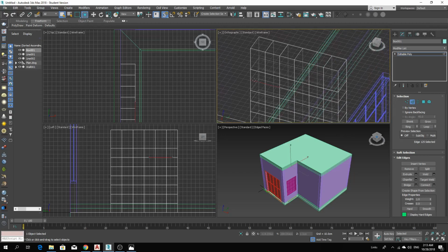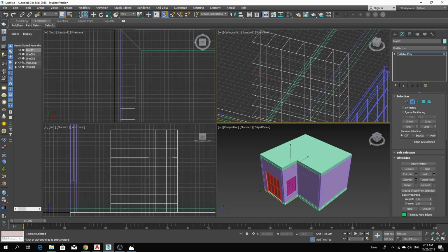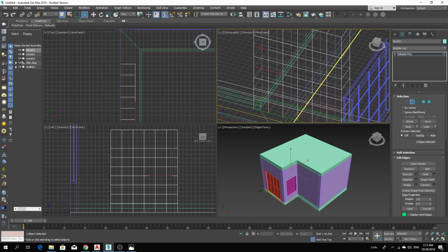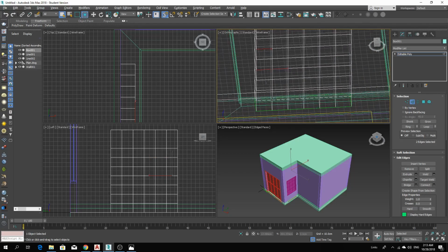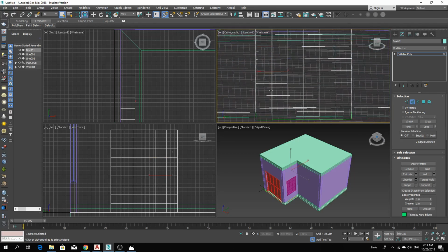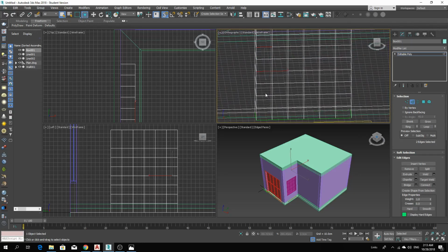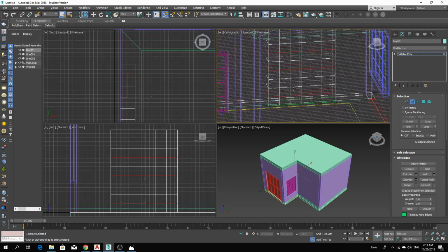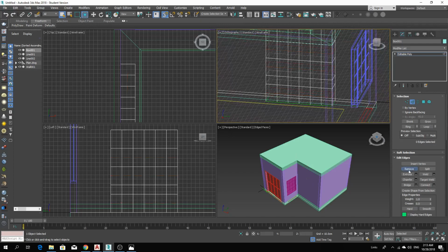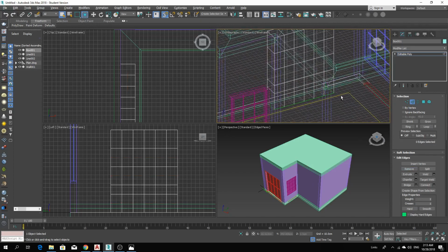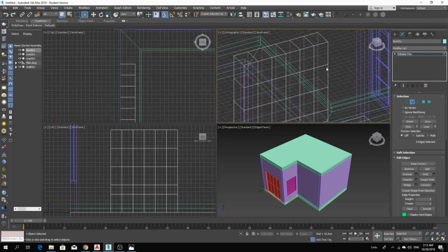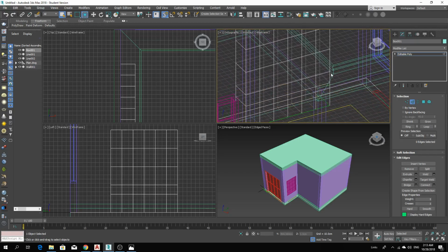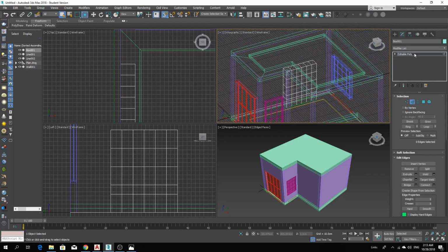So I'm just gonna select each other horizontal segment there, and then leaving this one, and then taking it here and going to loop and then remove. Okay, so now we have a 44, 44, 44, 22, 44.